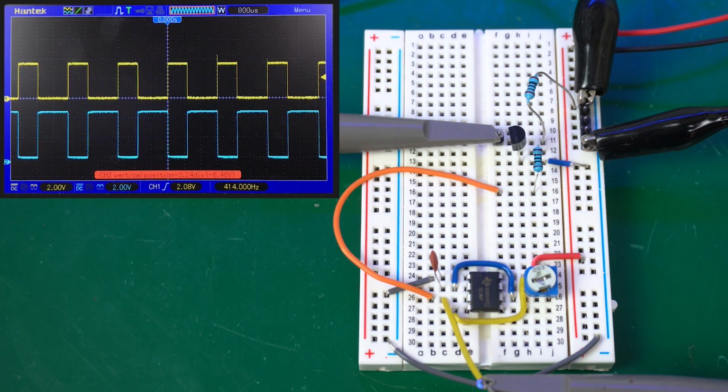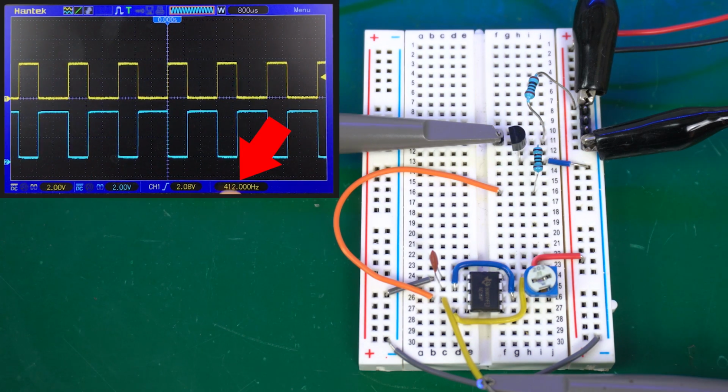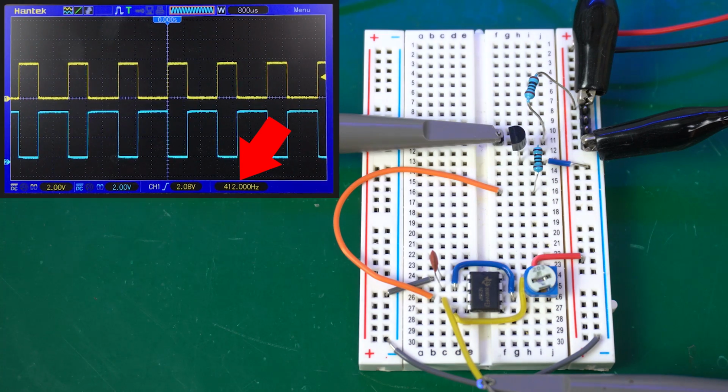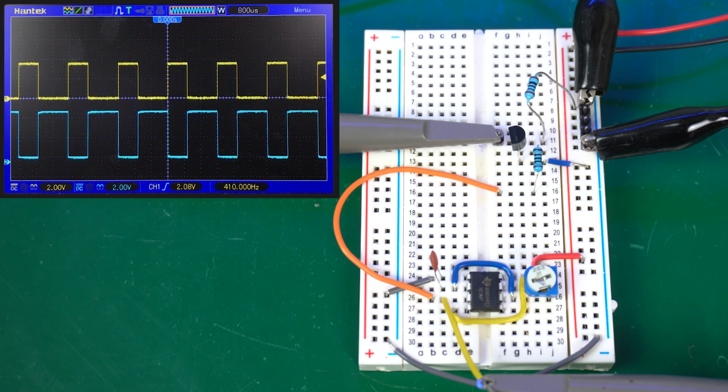So does this mean that we can just go ahead and use this on the Amstrad? Not quite. We're sending a square wave to the transistor, but it's really slow. This is only about 470 Hz, and on the Amstrad it's going to be 4 MHz, which is almost 10,000 times faster. The 555 timer can't create a 5 MHz wave, but it can definitely go a lot faster. I believe it can reach about 500 kHz.